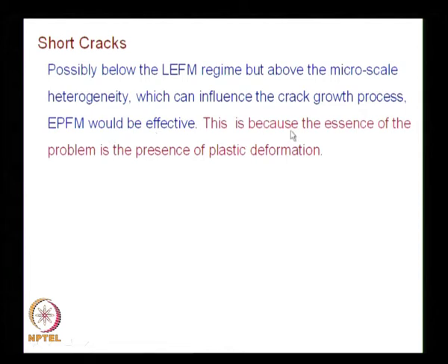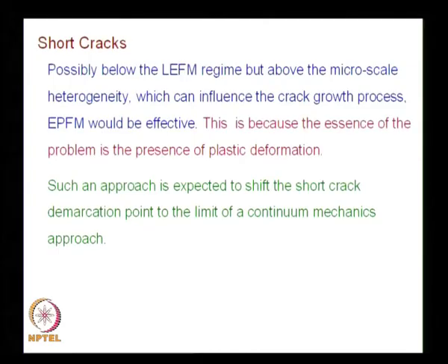This is because the essence of the problem is the presence of plastic deformation. So, from LEFM, if you go to EPFM analysis, you could analyze still smaller cracks, but it does not start from 0. Then you have this micro scale heterogeneity and so on. So, the use of EPFM is expected to shift the short crack demarcation point to the limit of a continuum mechanics approach.